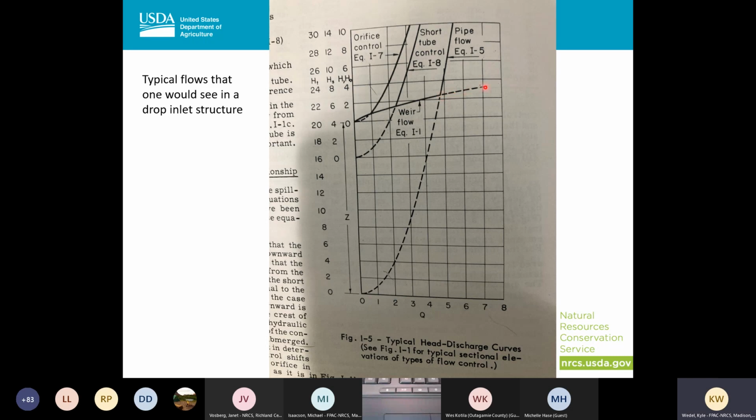And then once I get past here in weir flow, because we'd be in pipe flow, that water will back up into the pipe, and it won't allow that air vortex that we talked about on the previous slide to enter there. So it can't be in weir flow after that point. So we're dealing with this upper section. And this is where these structures get a little confusing.